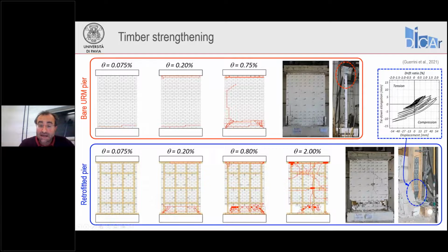You see the section here is significantly reduced, almost to half the initial one, and probably this is what induced this cracking here, where the masonry was basically falling apart, with these diagonal cracks that might be related to the transfer of shear along this diagonal.